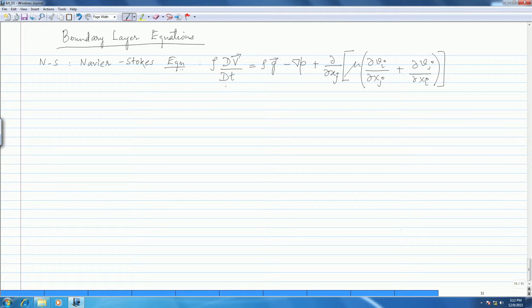This term is basically the total derivative of the velocity, which has the instantaneous component as well as the convective component. When we expand that, we will get that. Now, it's very important, and I always do this, that every time we say Navier-Stokes equation, it's not just a bunch of letters and symbols. One really needs to understand what the equation actually means. It makes life simpler. Now, if you look at this term here, this is dV/dt, the total or material derivative of the velocity, and you multiply that by rho. Think of this as a mass, multiplied by a volume.